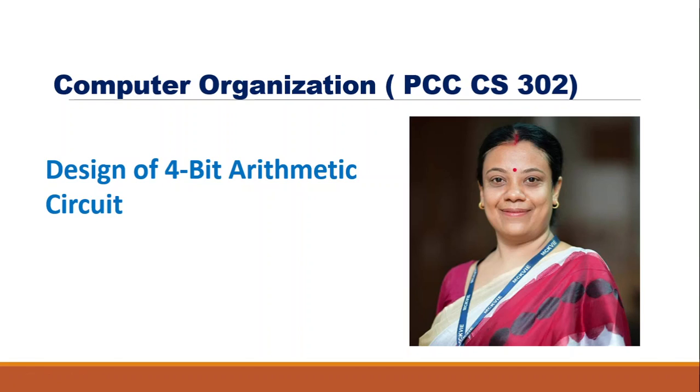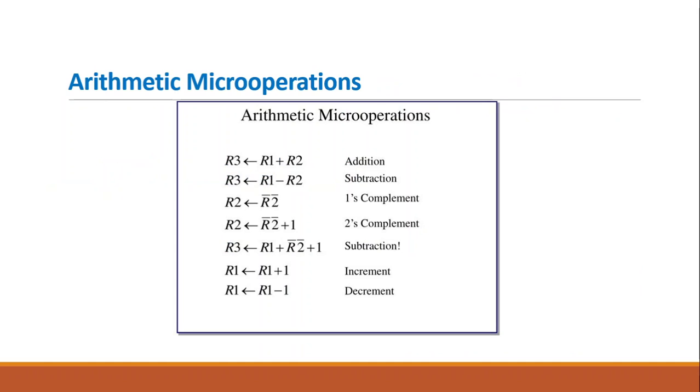Today I will discuss the design of a 4-bit arithmetic circuit. Before discussing it, let us continue with the arithmetic microoperations. Arithmetic microoperations perform arithmetic operations on numeric data stored in registers. The basic microoperations are addition, subtraction, increment, decrement, etc. So, first I want to discuss the arithmetic addition microoperation.